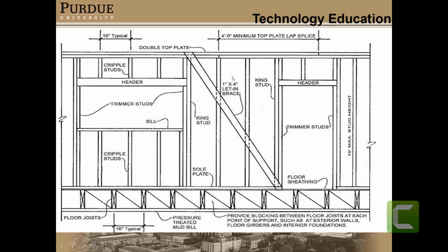The next thing I want you to understand is, let's look at this door framing right here. On top of this sole stud, you have what's called a jack stud or a trimmer stud. On site, most people will call this the jack stud. This is what supports the header. The header comprises two 2x pieces and a piece of plywood that goes down the middle. That makes your 3.5-inch width.